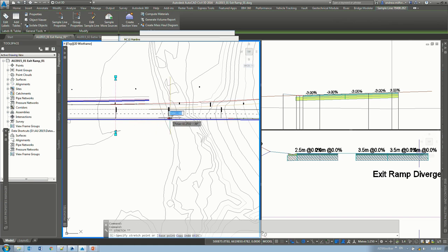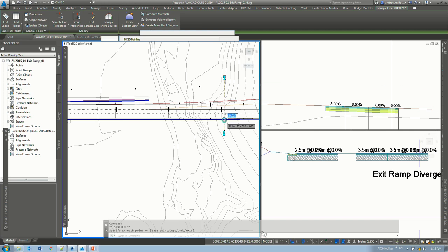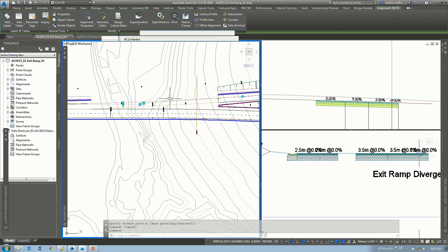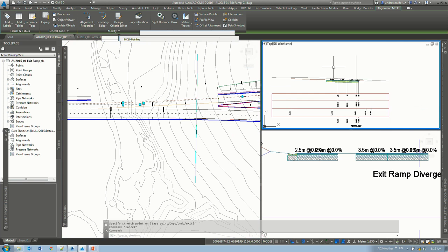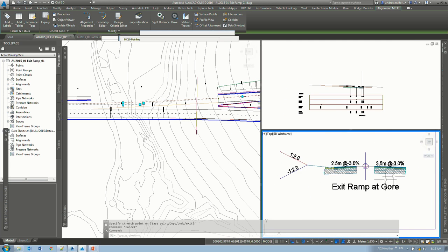If I run this through, you can see we're starting to develop the super elevation through this area. Trying to match MC30's super elevation to that value and get it to line up exactly is going to be near impossible. So what I'm going to do is use the values of these temporary planes and that slope projection tool to drive the slopes through that curve. That's where we're using this here.